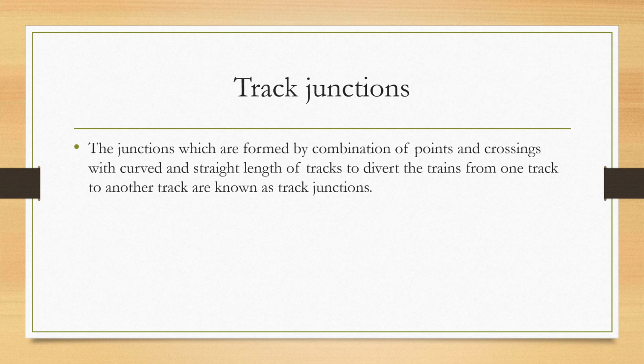Ballast and drainage. There should always be a sufficient quantity of good and clean ballast for proper drainage of the tracks. Interlocking connections. All interlocking connections should be tight and clear of ballast for their proper functioning.